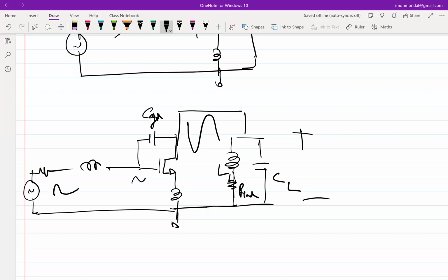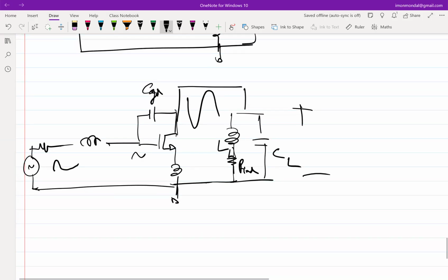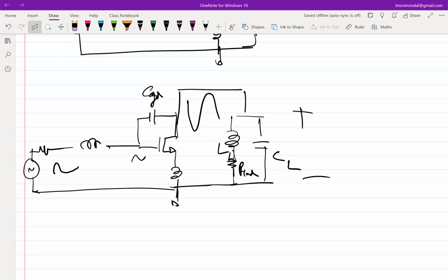based on the gain that you require, which means you are going to have these CGD interactions. And this can be substantial if the gain is high. And the effect of this, I will not prove this, you can do the algebra to figure out. But intuitively, you can think of the effect of this CGS and the effect of this CGD as coming in essentially parallel.